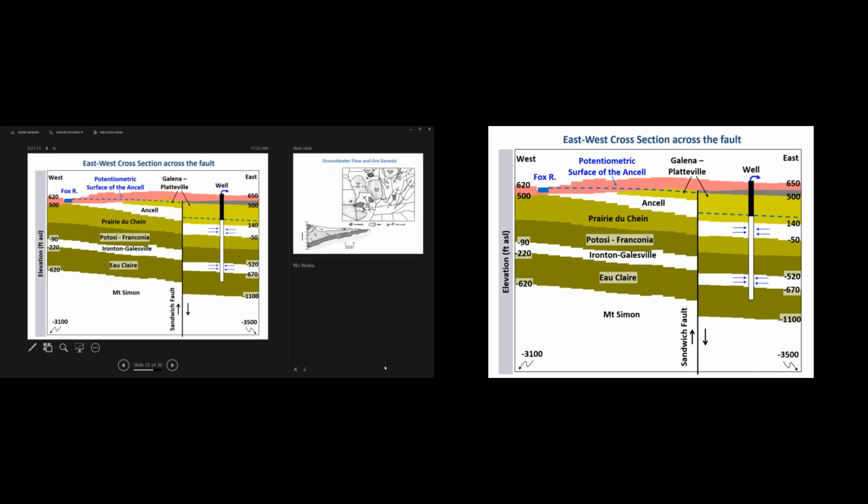And so you think, oh, if something is pinching out or something is offset, I won't have flow. The model will automatically assume that there's no flow. That's not what MODFLOW does. So does that mean you need to adjust your layer structure on both sides? Does that mean once you hit the Sandwich fault zone, layer 5 on one side is the end cell, but on the opposite side of that, you model it as the Galena Platteville, or layer 7? You can do that. Is that how you would address that? You can do that, but it gets difficult as the offset becomes less and less.